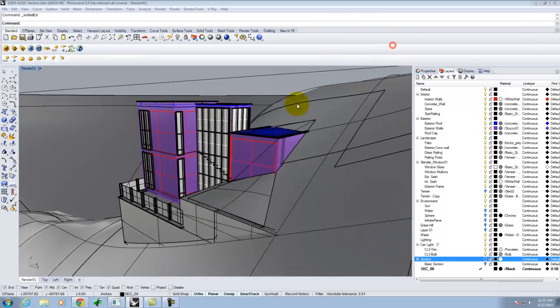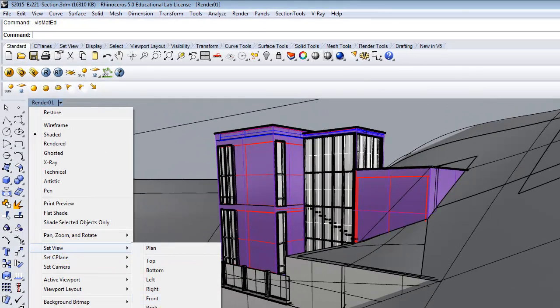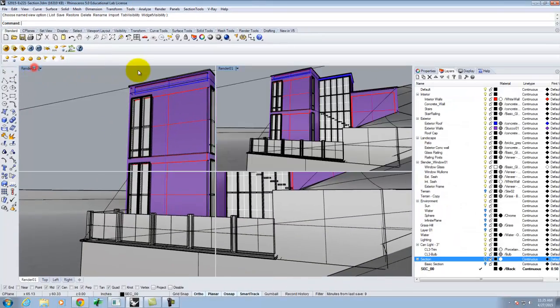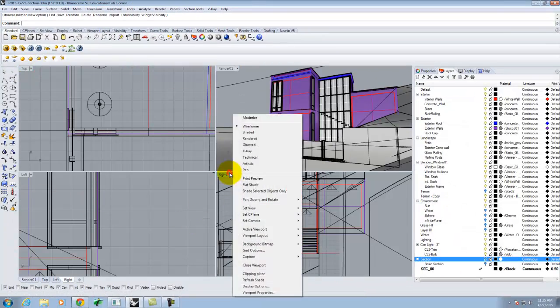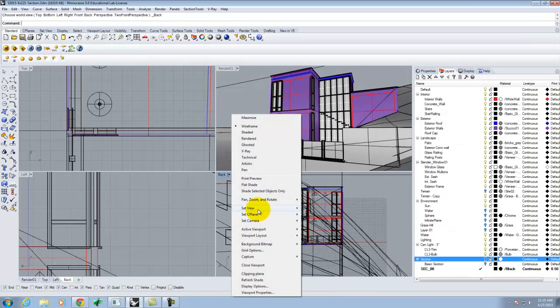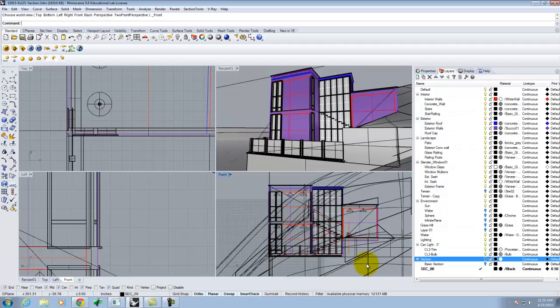All right. OK, so I've done all that work, and I'm now set back up. If I go back to my Set View, Render 1 view, right, when I do this render, instead of seeing the front of this building, I'm actually going to see it as a section. Okay? So this is a sectional perspective view. I can change this to be an actual parallel projection if I didn't want to render that by going to my front view or my back. I forget which one it is. It'd be the front view. Set view front there, and do the render in this view. See how it's orthogonal? It would be a standard traditional section.